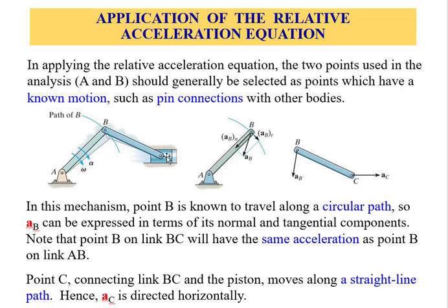As this is rotating, this is going to go to the right. AC is equal to AB plus the relative acceleration of C as seen by B, which has two components. The first one is alpha of this length BC cross product of R C relative to B, so this vector from B to C, minus omega squared of this BC, which we don't know yet, multiplied by R C relative to B. So not to forget.